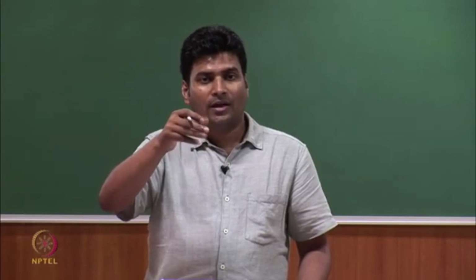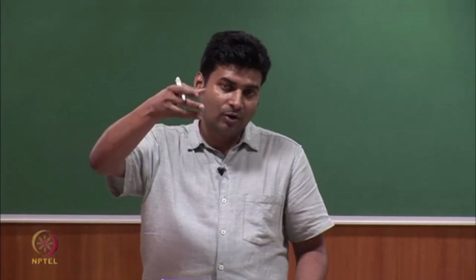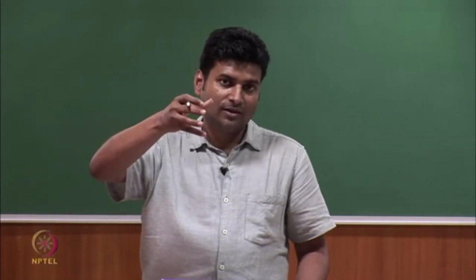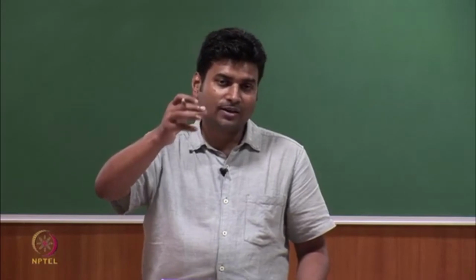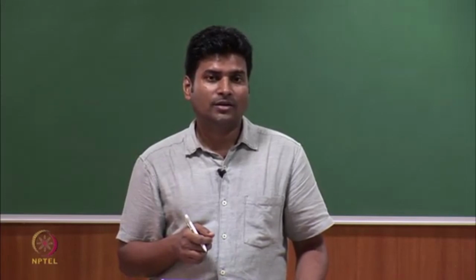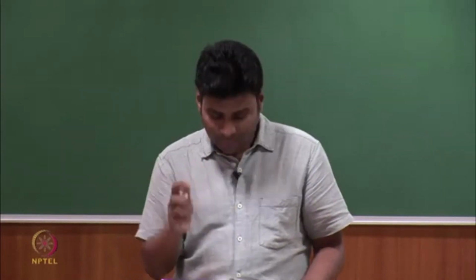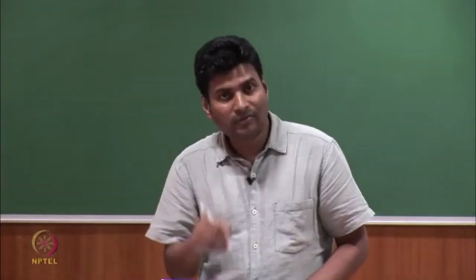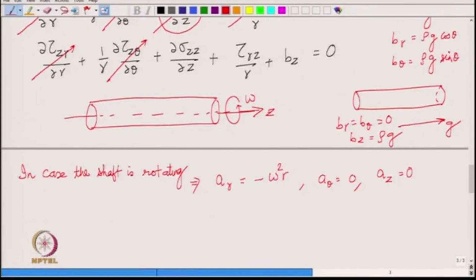And then in that frame the shaft will not be rotating, shaft will be static, but then the pseudo force has to be applied. So, instead of acceleration we will have body force, centrifugal force, pseudo force would be like the centrifugal force.